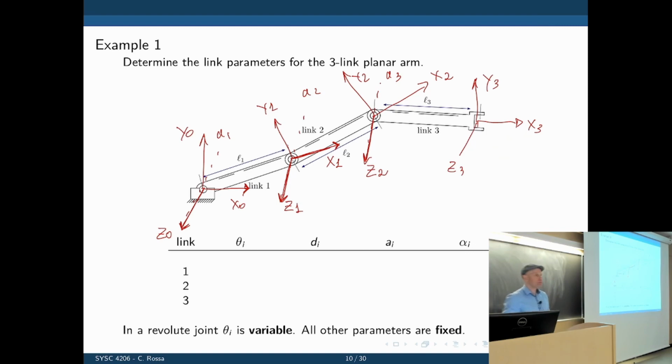Yep, these revolute joints are constrained to a plane. If you had a ball joint, you would choose that arbitrarily? Yes and no. We have to define two independent axes, one for the rotation one way, the other for the rotation the other way. As soon as you define those axes, then you know where the Z's are. We'll see that in the next lecture.